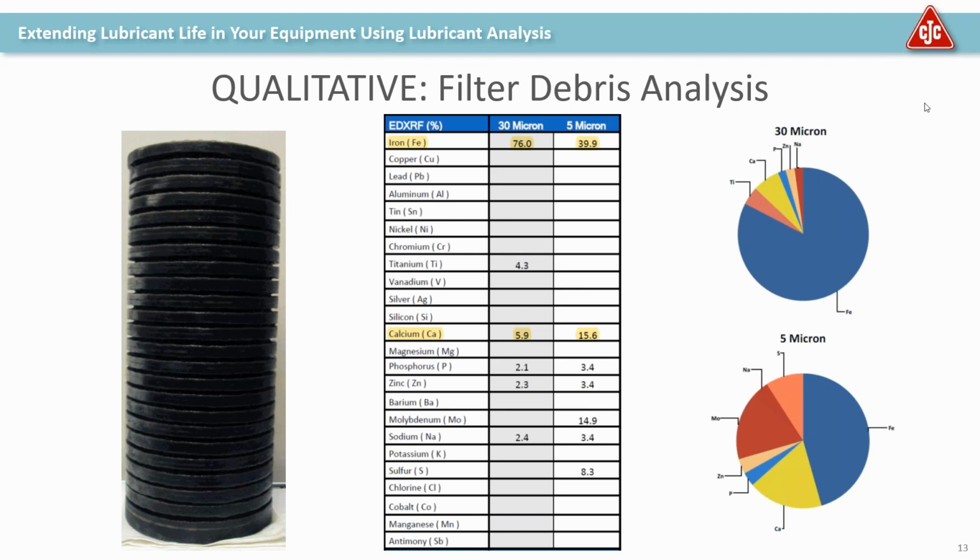Yeah, and then particles, we talked about it in your matrix. A lot of times the gearbox is so dirty that you won't even run a particle count in certain applications. But that can create a very catalytic environment where you see the rapid depletion of additives because all these particles are consuming that, and then further wear and tear. It's a snowball effect, and that can lead to poor heat transfer, and then increased viscosity, and things just go downhill rapidly from there.